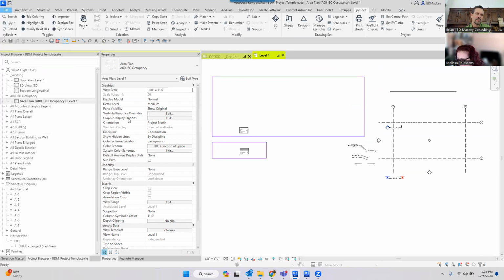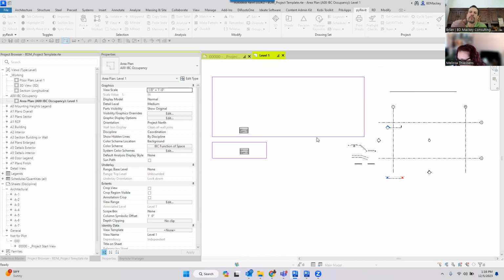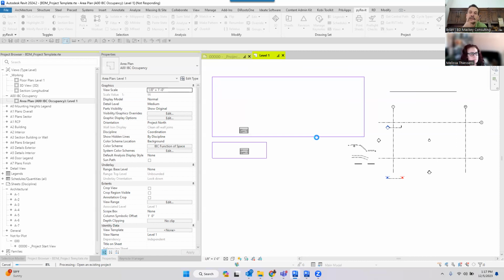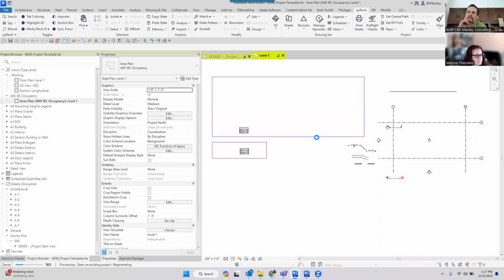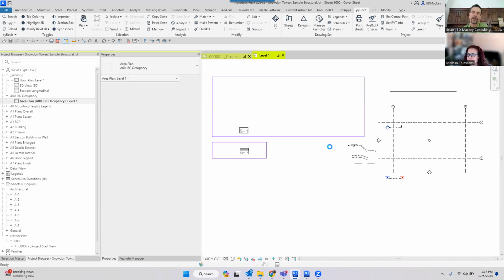Sample files. Let's go to the Revit structure. What Desiree means is a residential type area: how are we going to show where there's overframing on a roof or a truss? My one thought on this, and I don't know how well this is going to work, is that with the new load tools, we can actually do area loads, which will host themselves to the hosted object and update with the hosted object. So my thought was we could just do an area load, change the hatch pattern on the area load, and then use that for the look of the overframing. Obviously, it's probably not going to work perfectly if you're actually using the loads for engineering, because then you've got this weird extra load on there.